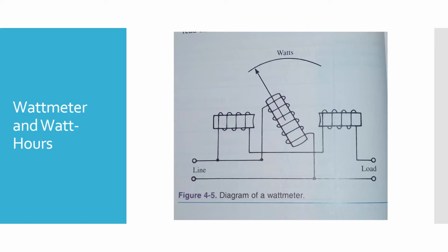The watt-hour meter is a complicated type of induction motor. It uses field coils in series with the line current and also field coils connected across the line voltage. An aluminum disc rotates within these fields at a rate proportional to the power consumed. The disc is geared to an indicating dial. The dial shows the amount of power used. To read the watt-hour meter, see Figure 4-6.